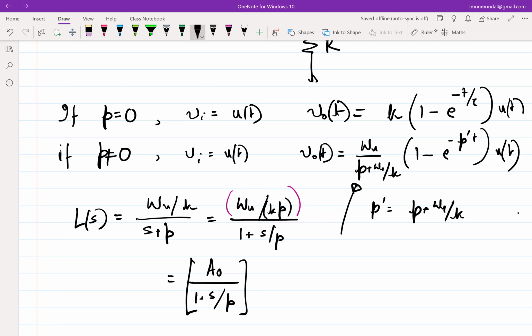So now if I take you back to your classic negative feedback topology, V naught is approximately equal to 1 over beta when A beta is much greater than 1. And when A beta is much less than 1, what is V naught? It is A times Vi.